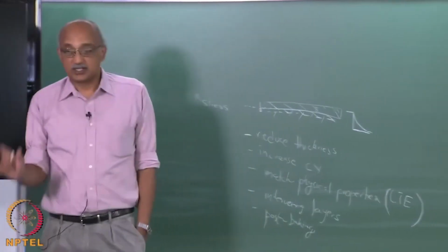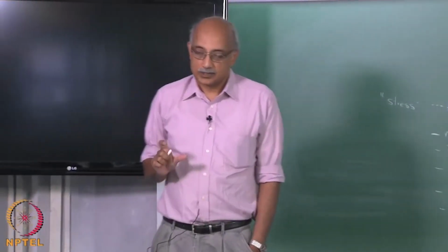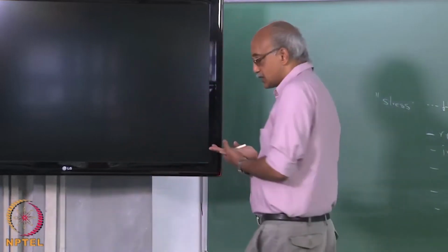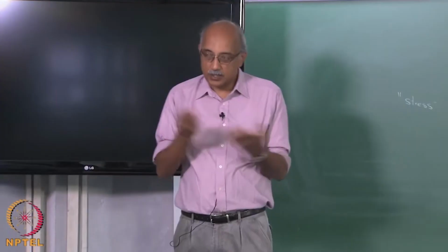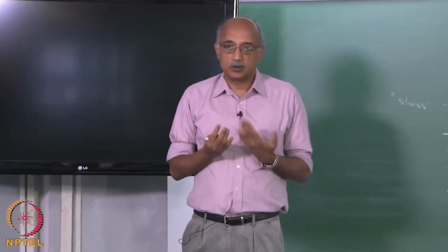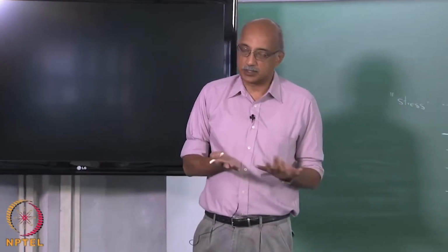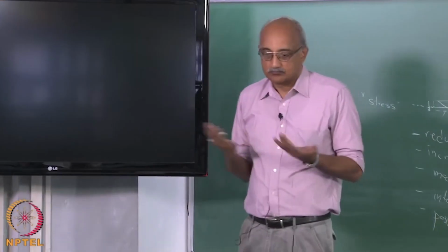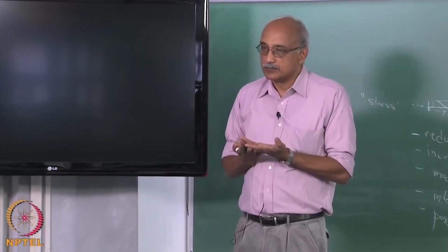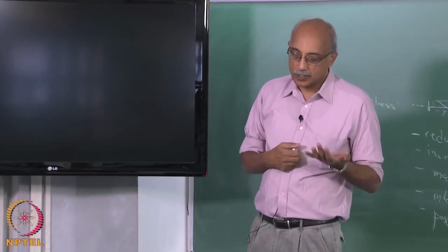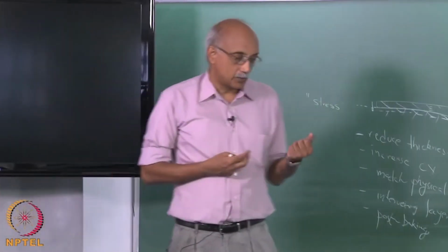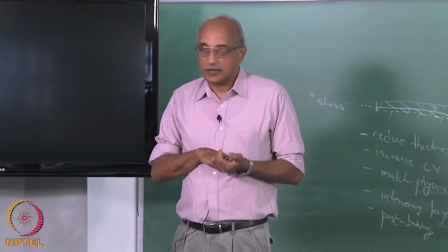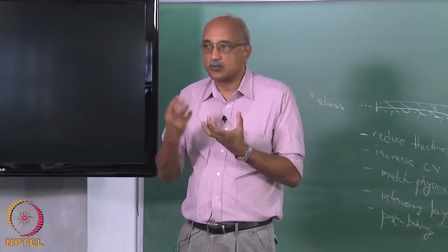This is important to control the structure of the deposit, because it turns out that one of the major differences between a coating and the substrate is the morphology and structure of the coating and how that differs from the morphology and structure of the substrate. So, for example, if you are trying to do, let us say, a metal coating on top of a semiconductor, the metal layer that you deposit, depending on the deposition conditions, can be a very amorphous structure, or it could have a more rigid structure to it.